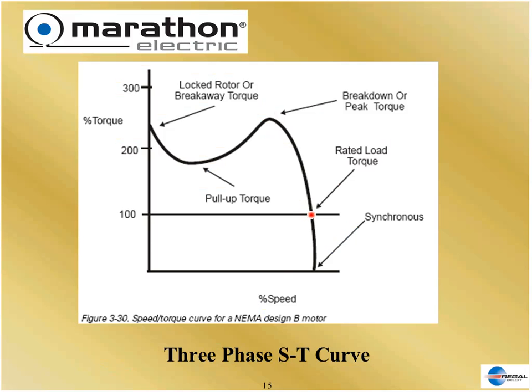That point is where the motor torque is equally balanced by the load torque. And now the motor cannot accelerate, it simply runs there, and that speed is slightly less than the synchronous speed, the difference being the term slip.